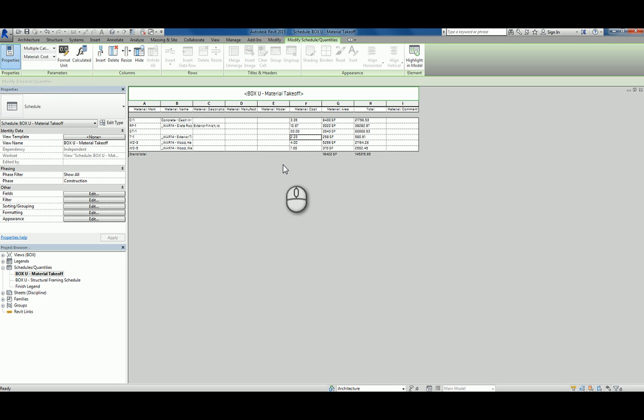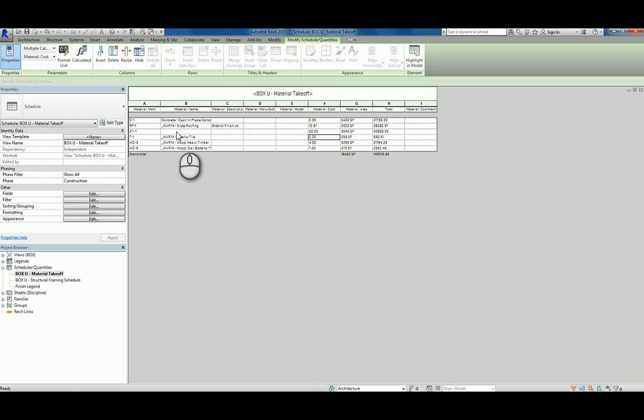So according to this material takeoff schedule, just these materials, which are the concrete, the slate roof, the stone, the exterior tile that was at the curbs and planter areas, the heavy timber, and then the wall battens, all of this stuff is going to cost $145,000 just for the materials. And it's Revit, so it's all instant. So if we begin to change this from $20 down to $15, then you see everything update.